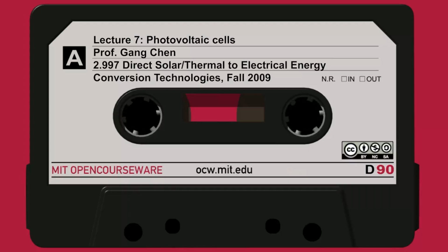Amorphous silicon doesn't work that way, so you have to have the electrode right on top of it. So it's a transparent conductor. And this is the cathode, right? The active region is about 6 microns.